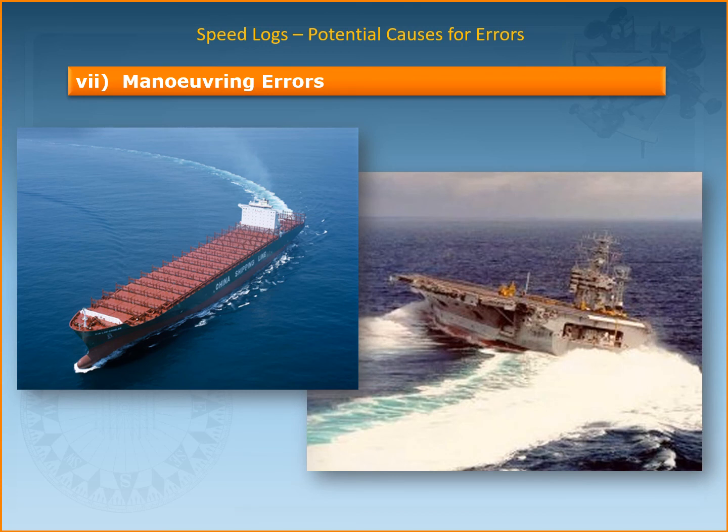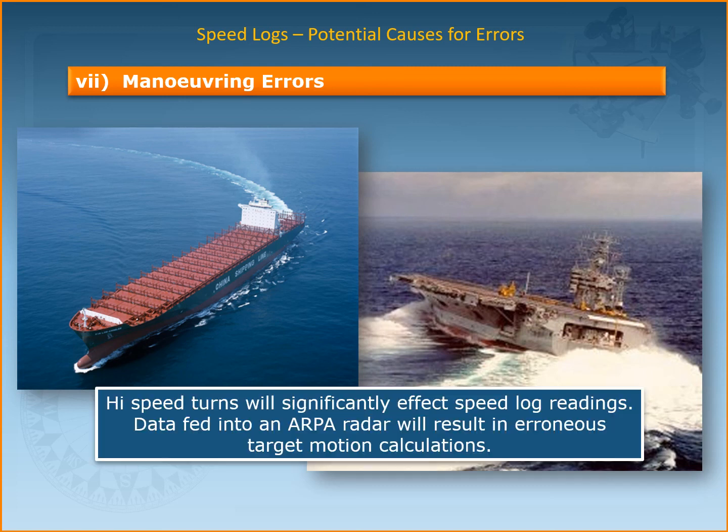Then we have the maneuvering errors, which may be significant, for example in the input to an ARPA or radar during a high-speed turn in a close quarter situation. So when you start turning the vessel at a high speed, the flow of the water across the transducer of the EM log also gets affected. In that case, you should wait for the vessel to settle down on a steady course, and then get the speed reading.